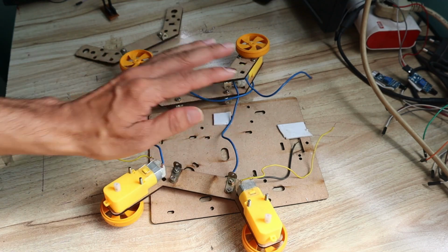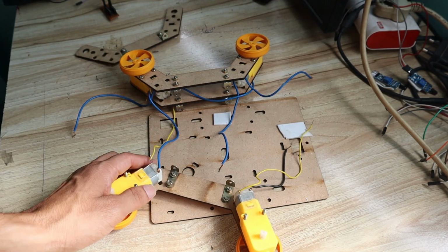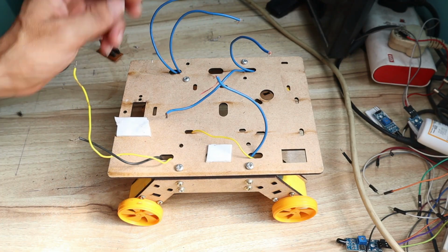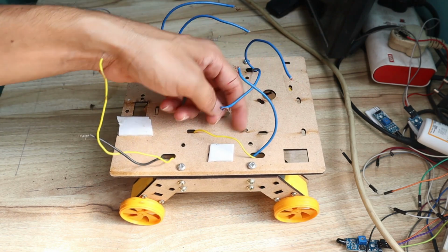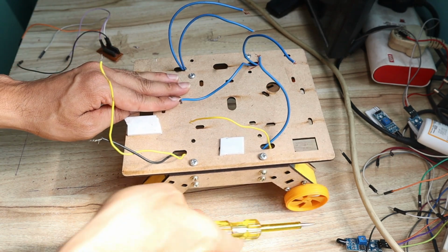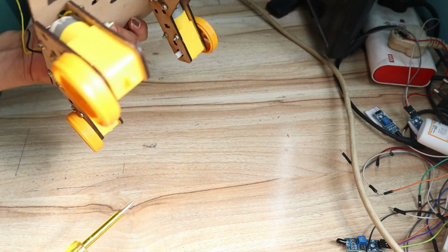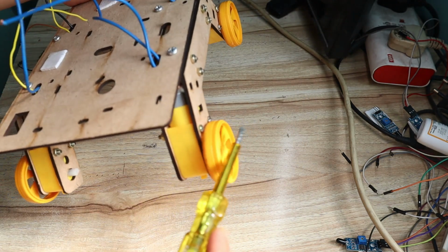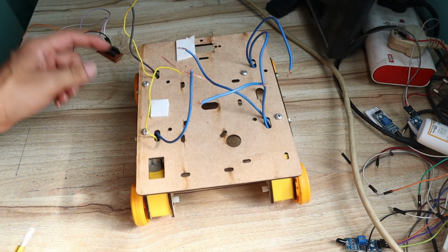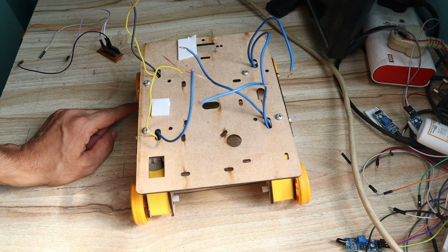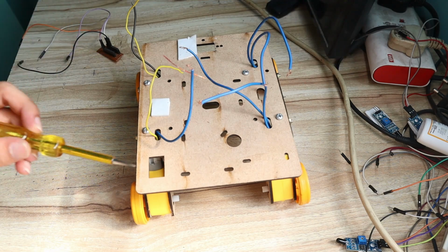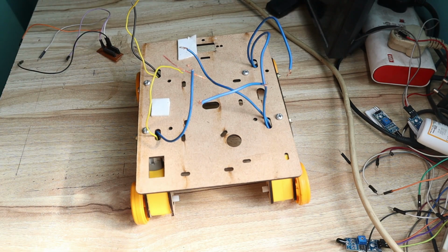Now quickly I will connect the chassis and bring this wire up. Once you have the 8 wires up for your 4 motors, you can see 8 wires are coming from my chassis. Now we have to find out the direction of the motors. There are 4 motors; these 2 motors are for the left side, these 2 motors are for the right side. When I give the supply, these 2 motors should rotate forward, and these 2 motors should also rotate forward. So the direction should be the same for each motor. How to find the direction, we will see now.